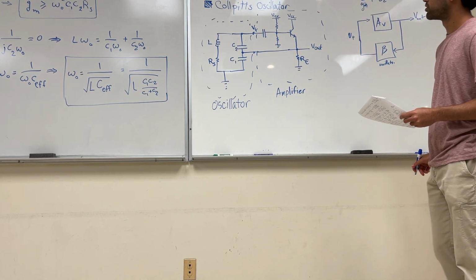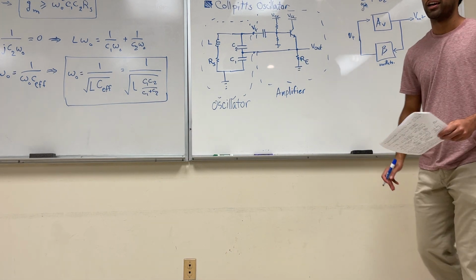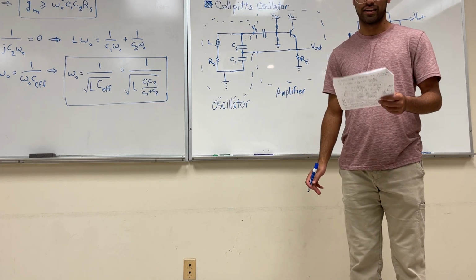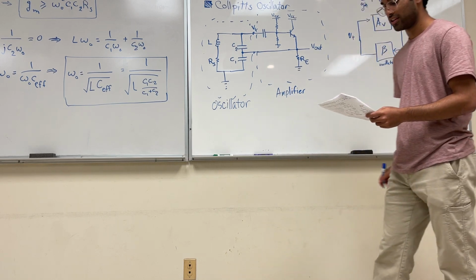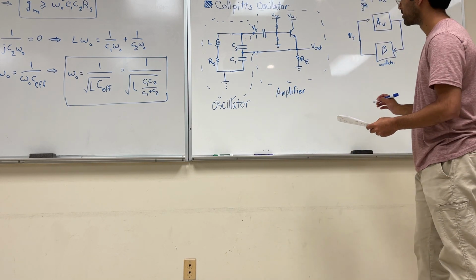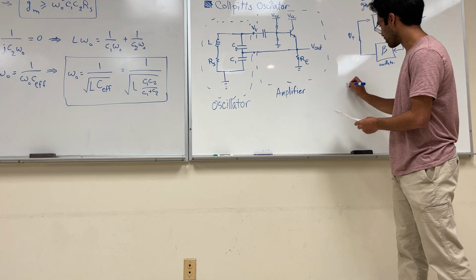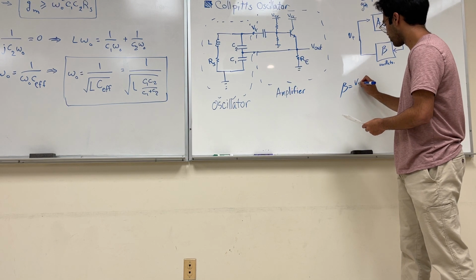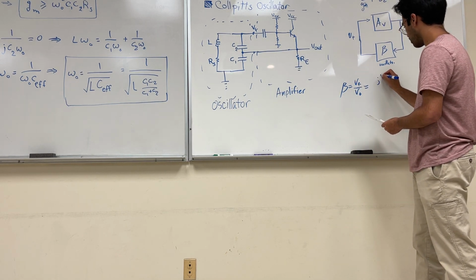And to do this, we can model the oscillator, of course, as a transfer function. I can do the derivation after if you want, but actually I'll include it in the lecture notes. It's not currently in it, but we'll include it. But basically, the gain of this will also be this. Beta equals VF over V naught equals jXL.